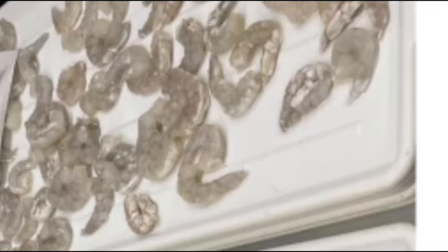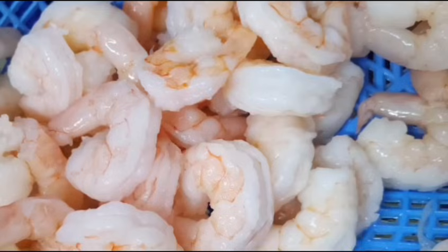The problem of freezer burn arising in cold storage is not only due to temperature abuse. Even though you maintain the temperature of the cold storages at minus 20 or minus 18 degrees centigrade, and you have a hot gas defrosting mechanism or hot coil defrosting mechanism, you can still encounter the freezer burn problem in cold storages. Why? Because of the fluctuation of relative humidity.